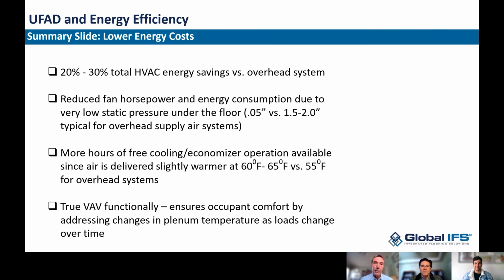a great strategy. So the other strategies that come into play, which are not necessarily limited to underfloor but really complement underfloor, is to use some kind of a mechanical cleaning mechanism, which is also recognized by ASHRAE. If you can do that and get rid of contaminants, you can make a case for less outside air in places where maybe you don't want outside air. If you're sitting next to a Port Authority bus terminal in New York City, you probably don't. So there are strategies around it, but again, the basic concept of flushing more outside air into a building does make sense. It's a benefit from ASHRAE's perspective.